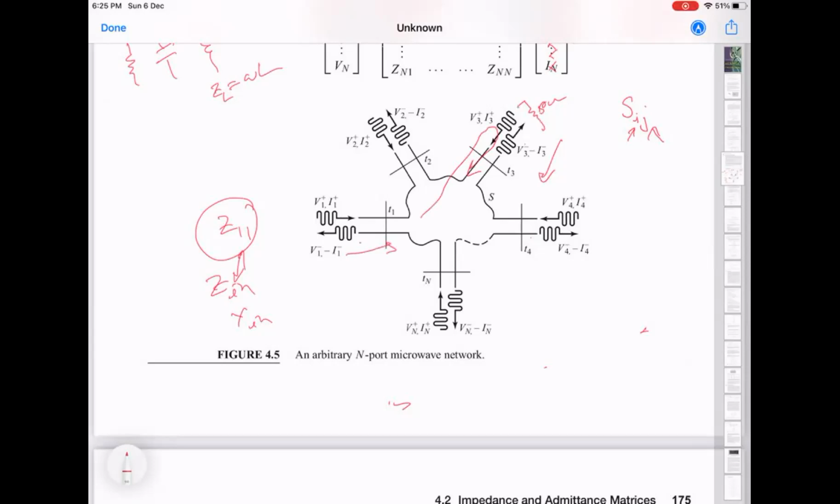Okay, so this is extremely important and practical information: if you are checking a multi-port device and seeing if it is working properly or not, you need to make sure that the ports are terminated appropriately. Now, sometimes you might want to keep it unterminated for some other reason, but by default, you should always make sure that it is connected properly. I'll just give you an example.